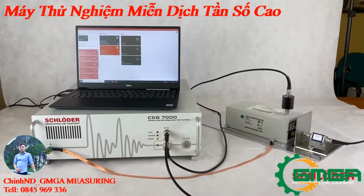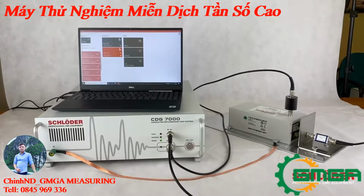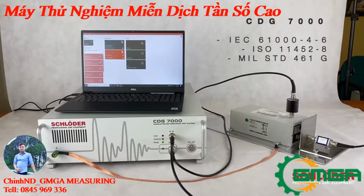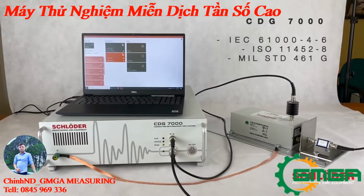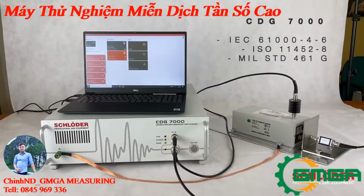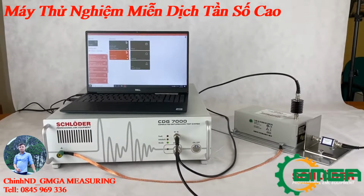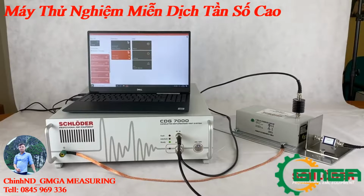This time I would like to show you the CDG 7000. This is our generator for conducted immunity tests based on IEC 61000-4-6. You can also use it for ISO 11452-8, and you can even use it for the MIL standard 461G. To show you the operation of the CDG 7000, we built up a test system required for level setting